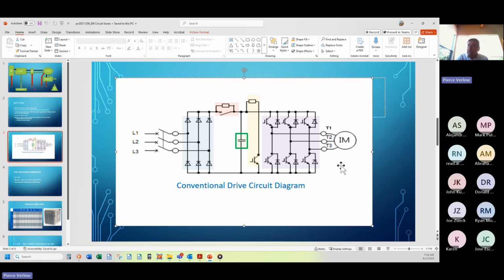When the load starts going down, the motor becomes an alternator. We send AC back to T1, T2, T3. We rectify it through these 6 flyback diodes and start putting power back on the DC bus. That DC bus rises up through the nominal 683 and then keeps going, and will keep going as long as this load is being lowered.